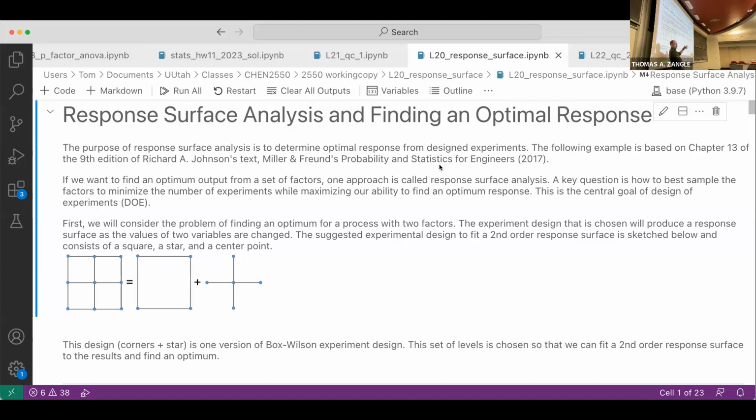So one of the things we have to do is autofocus, right? Something that your camera on your phone does automatically, but we have to implement this ourselves using our microscope. There we only have one factor, which is the position of our microscope relative to the sample, so the focal distance. And we measure a parameter. The parameter we measure is the sharpness of the image, or how in focus the image is.